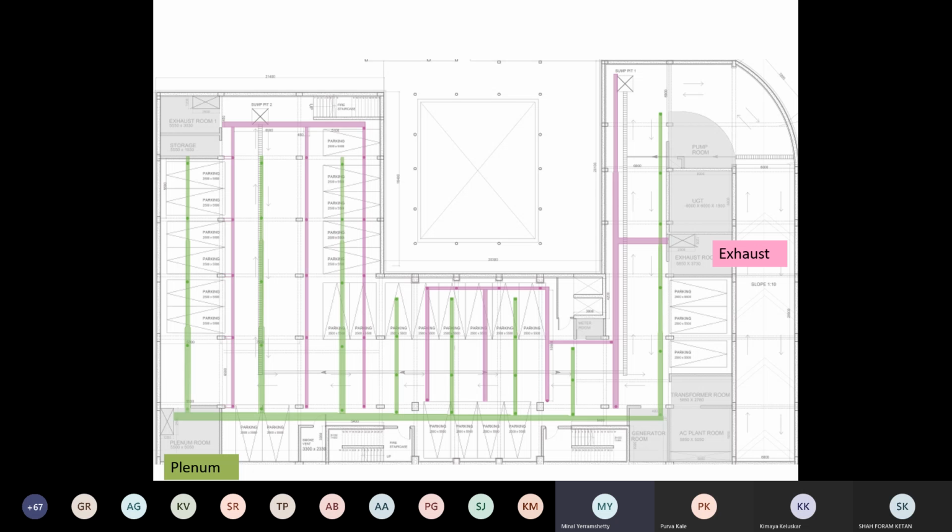a system. But I forgot to mention one part, and that is the exhaust. In exhaust, we are talking about carbon monoxide. Now, when I'm talking about carbon monoxide, monoxide does not tend to rise up because it is heavier. It tends to settle down. Now, your exhaust ducts are going to run along your ceiling, and your carbon monoxide is lying at the base.